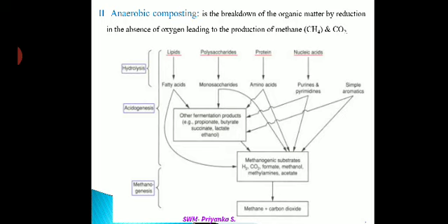So the second group of anaerobic bacteria starts fermenting and breaks down the product from the first group into simple organic acids. This step is called acidogenesis, the most common product of which in anaerobic digestion is acetic acid. This second group of microorganisms is described as non-methanogenic, or they are also called acidogens or acid formers. So this is the second stage.